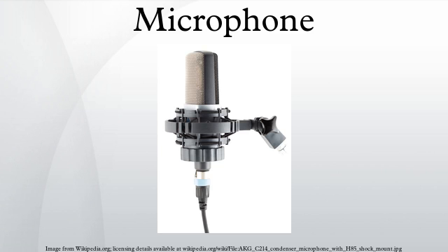The cardioid family of microphones are commonly used as vocal or speech microphones, since they are good at rejecting sounds from other directions. In 3 dimensions, the cardioid is shaped like an apple centered around the microphone, which is the stalk of the apple. The cardioid response reduces pickup from the side and rear, helping to avoid feedback from the monitors. Since pressure gradient transducer microphones are directional, putting them very close to the sound source results in a bass boost. This is known as the proximity effect. The SM58 has been the most commonly used microphone for live vocals for more than 40 years, demonstrating the importance and popularity of the cardioid microphone.